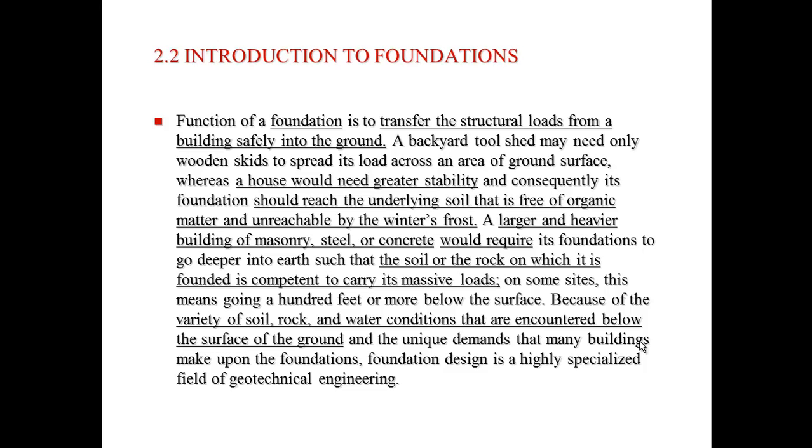The function of a foundation is to transfer the structural loads from a building safely into the ground. As buildings get bigger and taller and heavier, we need to think more and more about what's underneath the ground to support those. So we're going to be looking at different methods that we can use to support a building. There are some areas of the country where there is no bedrock within reach. We're going to end up putting down piles and caissons to support a building with a foundation on top of that.